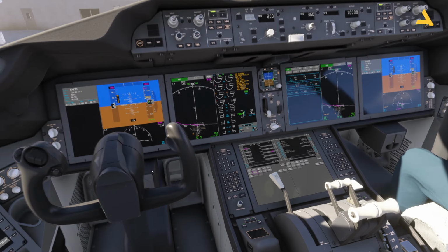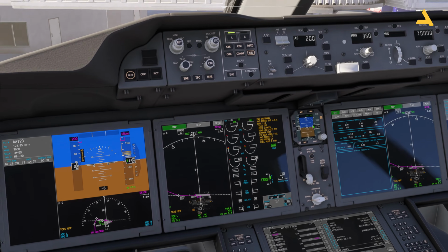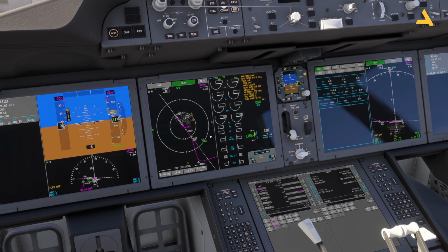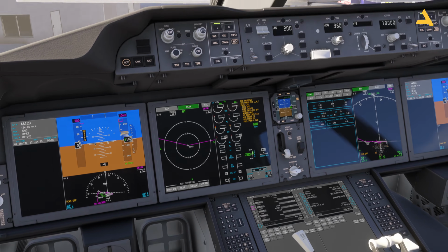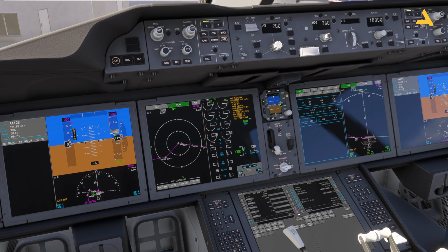Now you have the flight plan, and you can just get rid of the yoke. And if you go to this option plan, you can go through this complete flight plan by pressing this option step in this option legs. And you will see the complete flight plan over here in the navigation display. You can zoom in and zoom out by using this knob. And you will see that the complete flight plan is there, without any discontinuity or without any issues.